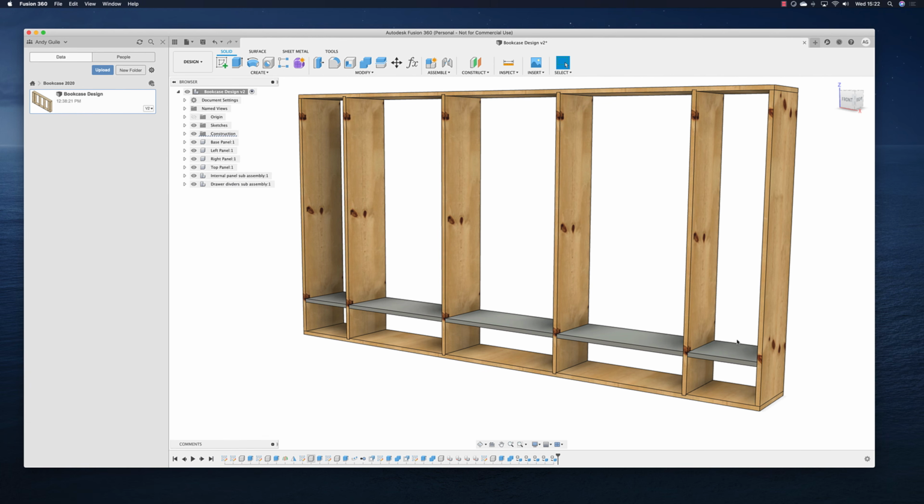Now what's super exciting by this, and that super quick way of creating shelves, is it's all referenced against this end panel here. That's what we drew on. So all of this as a single component is referenced from that. I cut the component by referencing these. So as these change and the positions of these change relative to each other as we redimension, the cuts will change and these will automatically resize. Let's see that in action.